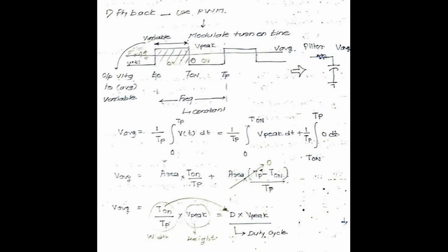The third advantage is that we can get multiple outputs from a single input, though this is also available in a forward converter. One big disadvantage is power: the thumb rule is that generally we use the flyback converter up to 100 watt.